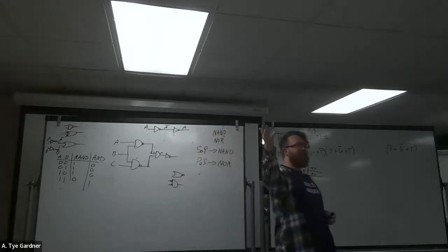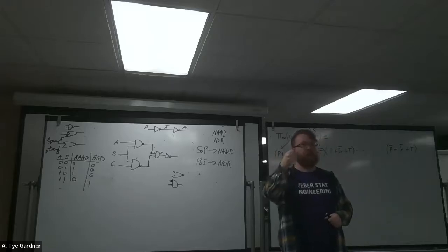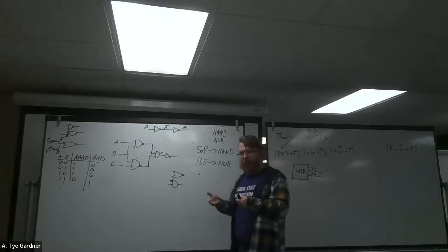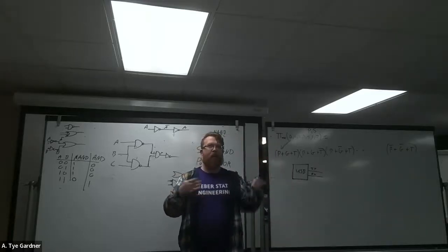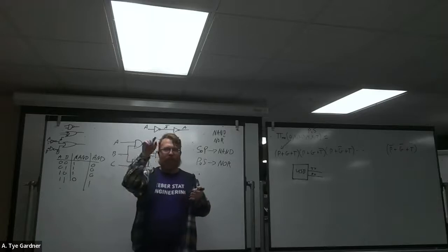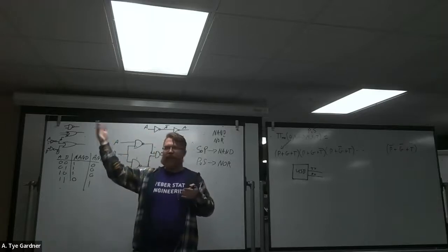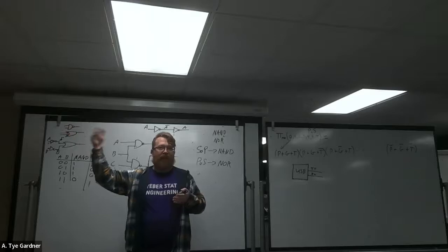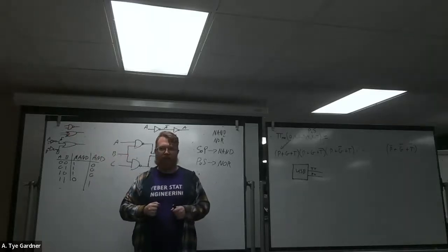And we can do analysis, right? What's nice is even if you were handed someone else's circuit and you were told to fix this, right? We have the circuit. It was built 40 years ago. We don't know why it doesn't work. Figure it out, right? All I would do in that case is write down the expression using a truth table through the intermediate signals. And then using my analysis techniques, writing those down, I would redesign it using min terms or max terms.